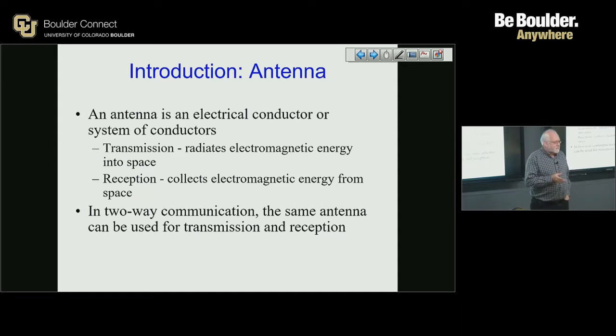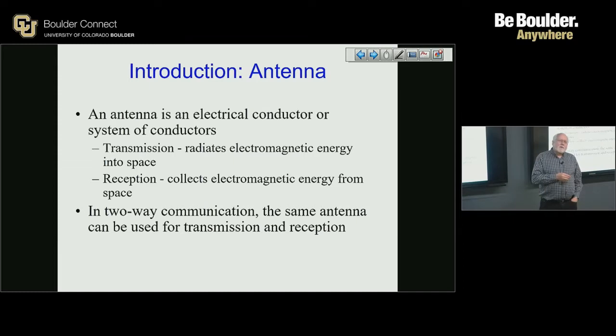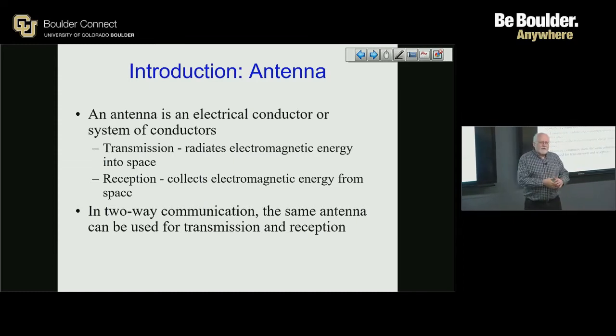Designing antennas is a magical art. The companies spend a lot of money hiring people. At my last company, we spent $140,000 buying software tools to do antenna design, because it's really an esoteric art. But the idea is that, as an antenna, you put power into it, it radiates the power out. When there are electromagnetic signals that impinge on that antenna, it turns it into a current that comes out the other side. What you really want on the transmit side is what's called good radiation efficiency, which means you want a significant portion of the power you put into the antenna to get radiated out as an electromagnetic wave.